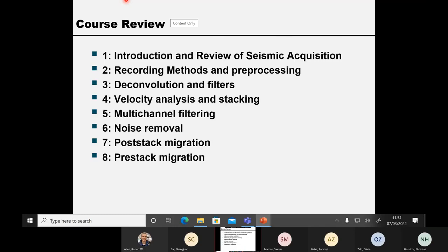But all this came from the example I showed you, the multiplication of two Z transform polynomials, okay? And I said that convolution and the filter actually are in different domains. Convolution means convolution in the time domain, but multiplication in the frequency domain we call filtering, right?